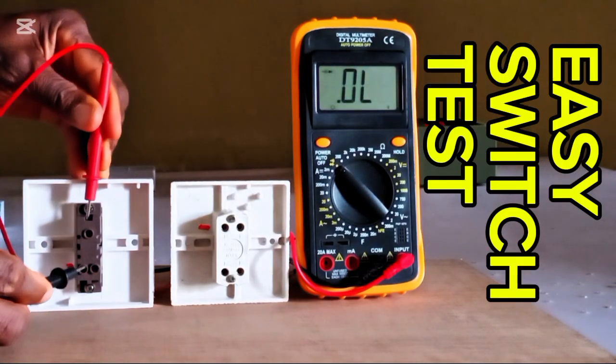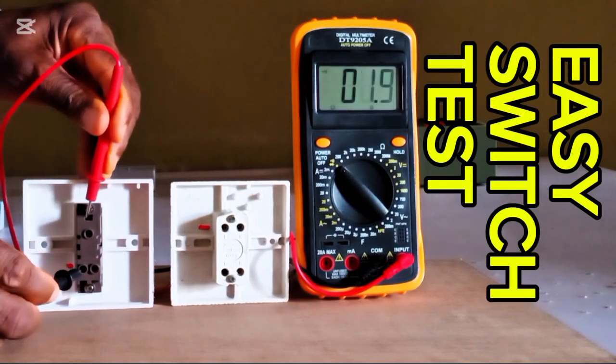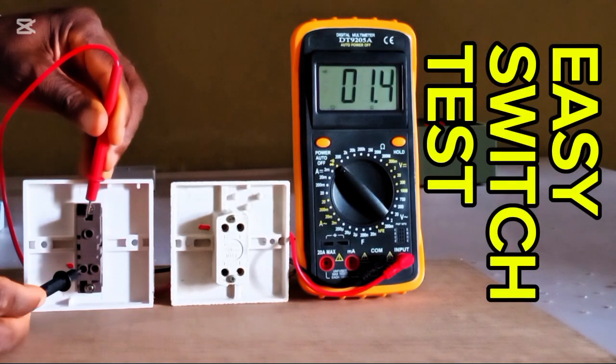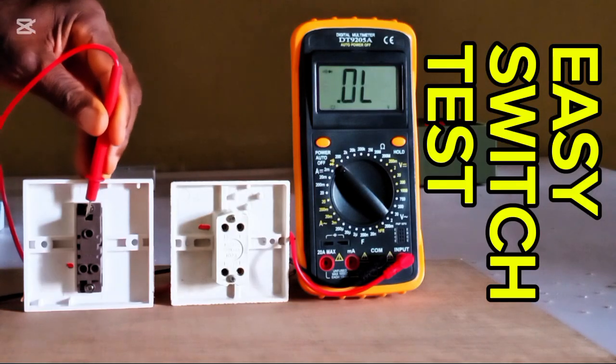If we flip this switch here, this one will go out, but this one will read. Good. But if common to line 1 fails to read in this flip, it means that internally the bar is open. It cannot make. Common to line 1 cannot make, and that is why it's unable to read.